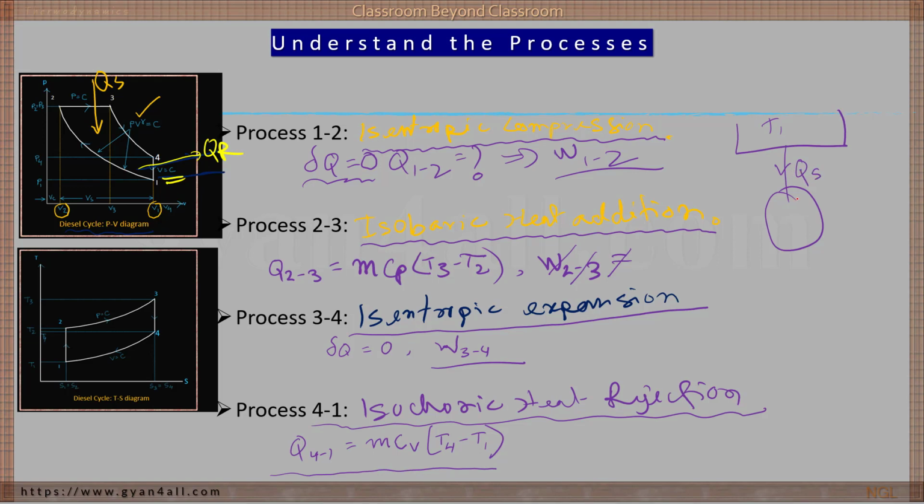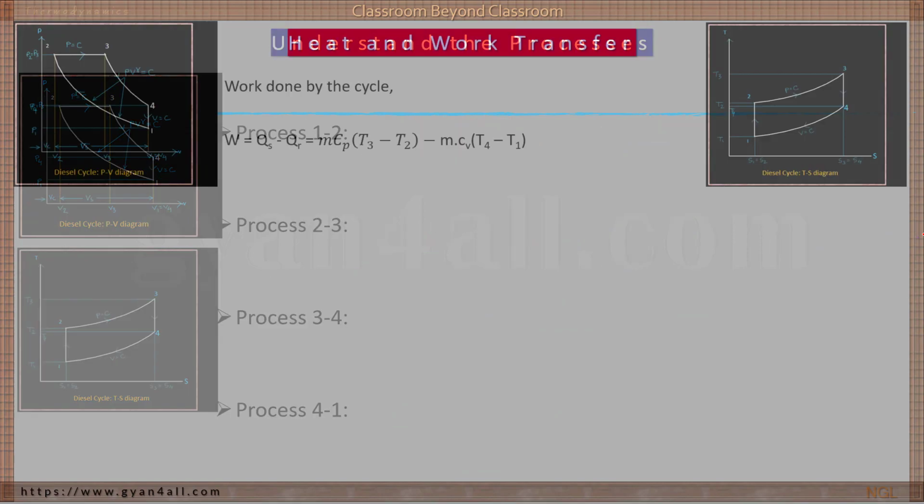Then this is a heat engine, and it rejects some amount of heat QR at a lower temperature, and the rest is converted to work, which we call net work output, that is equal to Qs minus QR. So from this formula we can find out the efficiency, and efficiency is W net divided by Qs.